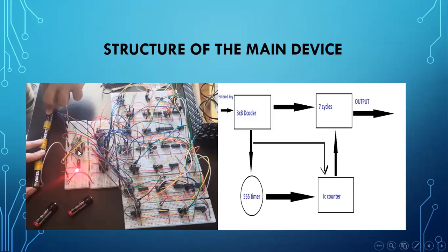The comparison is going to use an equivalent gate, which is XNOR. So XNOR is going to be high if both inputs are the same, and will be low if they are different.